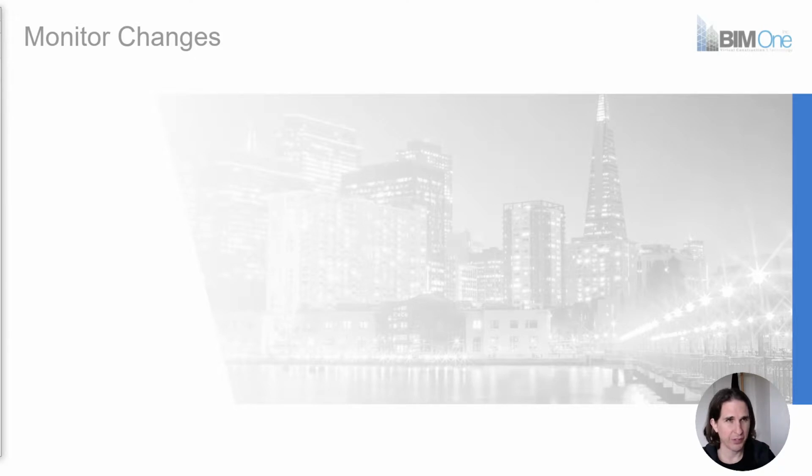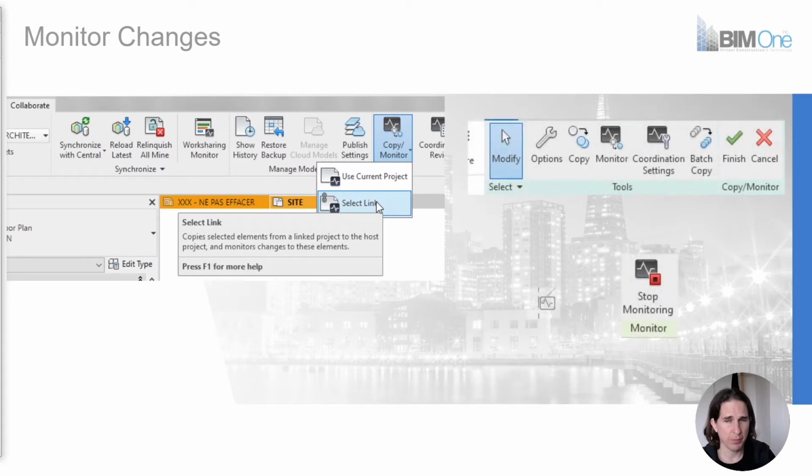One important feature in Revit is the copy monitor or copy monitoring, so that you can monitor the changes. So when you're using the copy monitor, once you select your link and then you grab all your grids and levels, you can grab these levels and make sure that you get to monitor them during the life of the project by using these options. So you will be notified of any modification to this element when opening the master file afterwards.